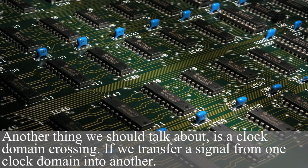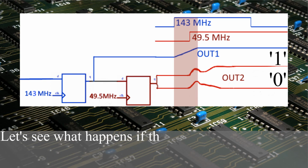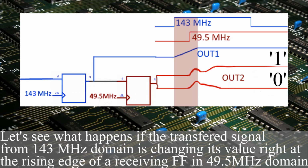Another thing we should talk about is the clock domain crossing. If we transfer a signal from one clock domain into another, some critical issues can happen. Let's see what happens if the transferred signal from 143 MHz domain is changing its value right at the rising edge of a receiving flip-flop in 49.5 MHz domain.